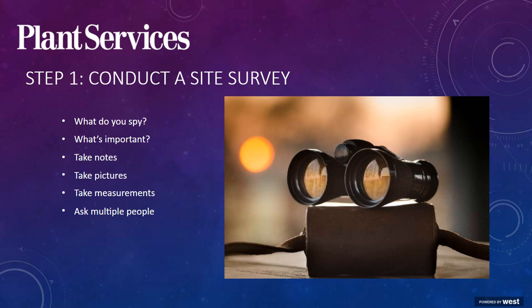And while you're there, do some spot measurements of pressure throughout the facility so you can see what the initial pressure profile is and if you really need to measure various points in the plant. Ask questions. In most cases, I ask the same question to multiple people in the plant: engineering, production, maintenance, management. What I find is even the guy driving the fork truck who's doing shipping and receiving, they notice something about your compressed air system, and they want to share it. So in many cases, you're going to get different responses to these questions, and it's just perspective, but it's going to help establish priorities for your project.